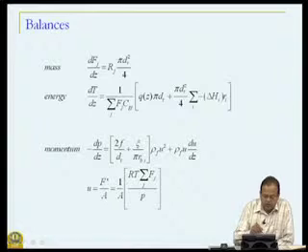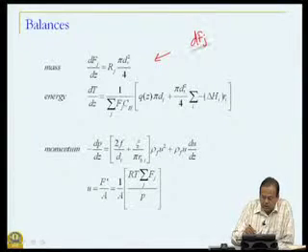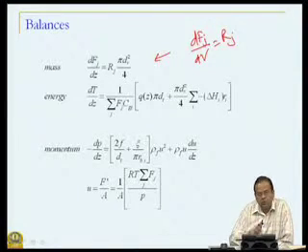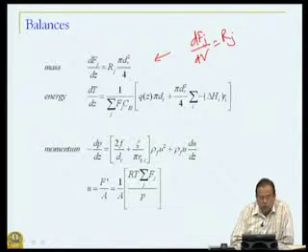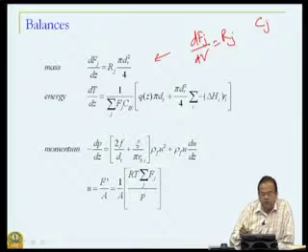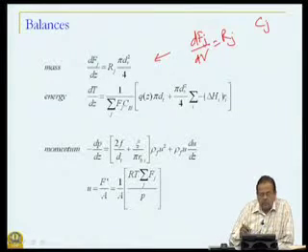Now, what is this mass balance? This mass balance is actually the same thing as dFj/dV equal to Rj that we had seen earlier. We are assuming only a tubular reactor. Now, why are we dealing with Fj and not concentration Cj? The reason being, if you recall, when we talked about stoichiometric tables, we have an increase in the number of moles.